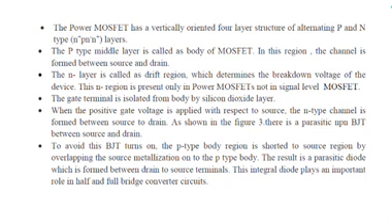This power MOSFET has a vertical 4-layer structure with alternating P and N type layers. The P type middle layer is called the body of the MOSFET, and the N layer is called the drift region. The gate terminal is isolated completely from the body by a silicon dioxide layer. When a positive gate voltage is applied with respect to the source, an N-type channel is formed between the source and the drain. To avoid the parasitic BJT, the P-type body region is shorted to the source region by overlapping the source metallization onto the P-type body.